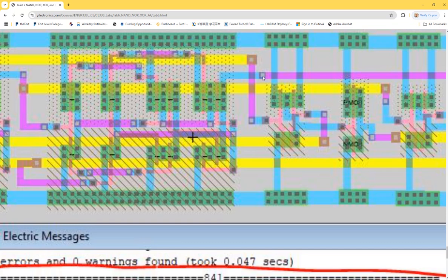Sometimes you have metal 1, metal 3 horizontally, and you want to cross it. You just have to route it through a different metal layer in order to not short it to the other traces. Okay, so the purple color is going to be metal what? 2. Because yellow is metal 3, blue is metal 1, purple is metal 2. That's all the 3 metal layers we have for C5.